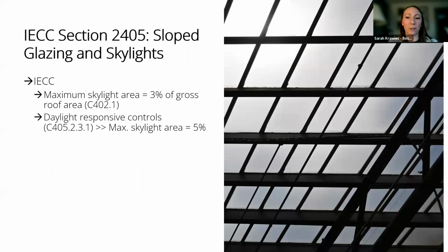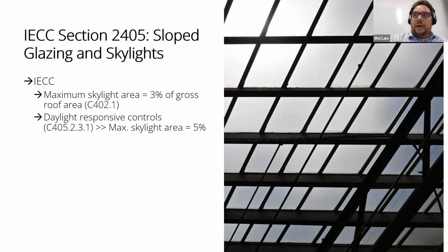Before we move on, we do have a question from Richard asking, what is a screened skylight? So the code describes screening. Underneath monolithic glass, under some situations where you may not have heat strengthened glass, you have a screen that is designed to structurally retain glass breakage below the skylight. I have never seen that. Perhaps I'm misinterpreting that, but I think most of the time when folks are considering the design of slope glazing, they don't want something visually interfering. So I can't think of an application where I've seen that before. I've certainly seen safety appliances or materials applied on the exterior side, but not on the interior side.